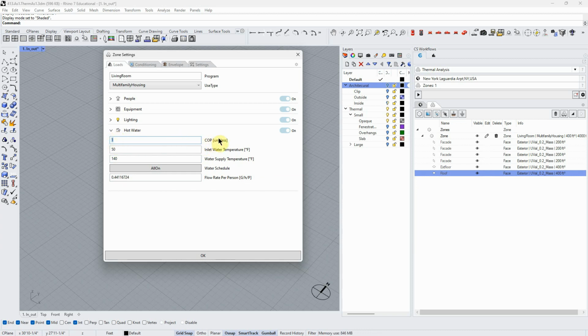This is a really important unit here, COP. So let's talk about it for a second if you haven't heard of it before. COP stands for Coefficient of Performance. For example, in Local Law 97, if you have a building that you need to upgrade to that standard, and you don't want to do a bunch of intervention on the architecture, the first thing you're going to look at is how do you save energy with your mechanical systems. And COP is a very basic metric for that.